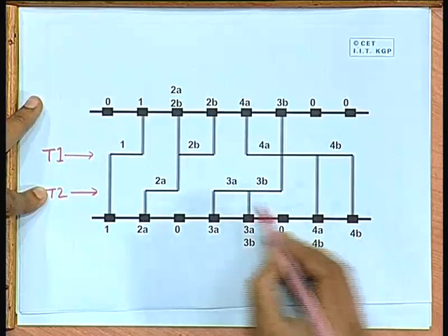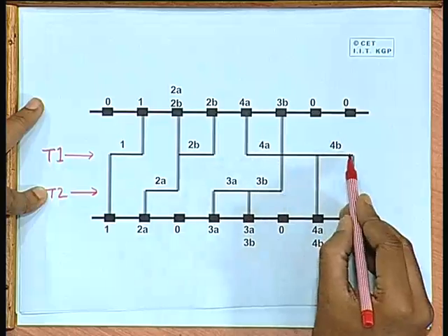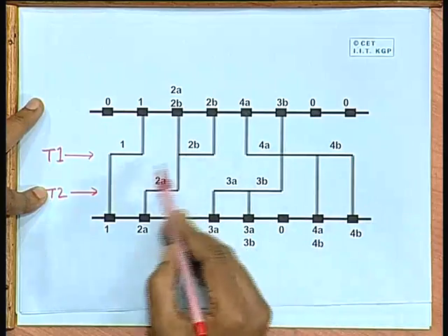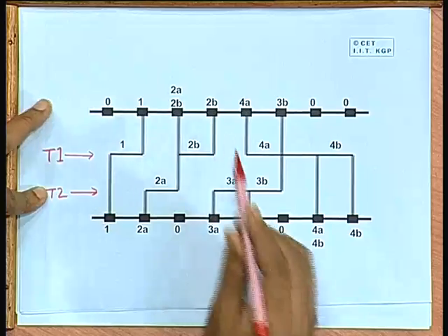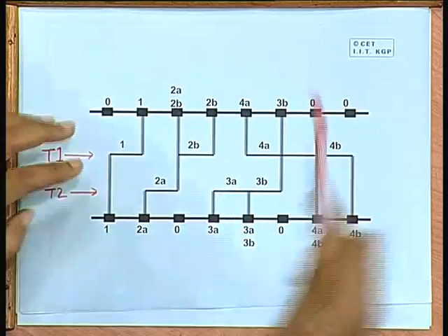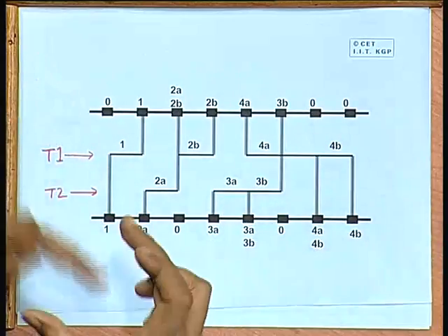So, you see in the final solution some of the nets are not split across tracks, but some of the nets are. So, the basic Dogleg algorithm tries to minimize the number of channels by putting the different segments of the same net across tracks. This is the basic idea. Okay. So, in the absence of cycles in the VCG, this method works pretty well.